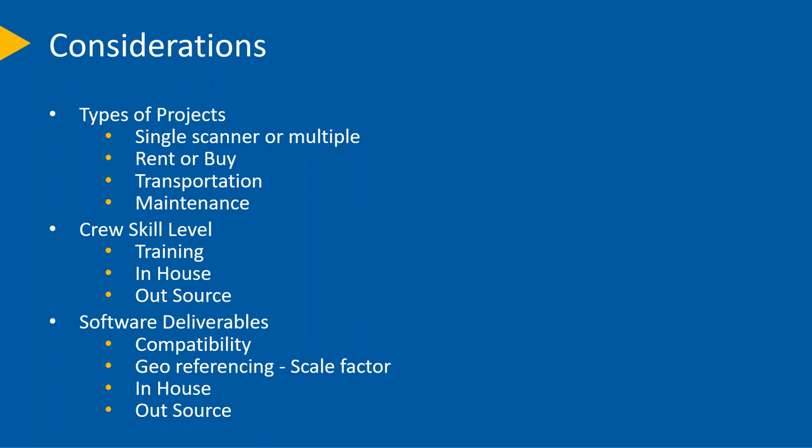You can have georeferencing, where you can just pick a point and assign a coordinate to it, and it may be close. Whether you're truly in a coordinate system or not is debatable at that point. Or there is really true georeferencing, where you're applying these scale factors. And then again, just like with outsourcing scanning, you can do the software deliverables in-house or outsourced.